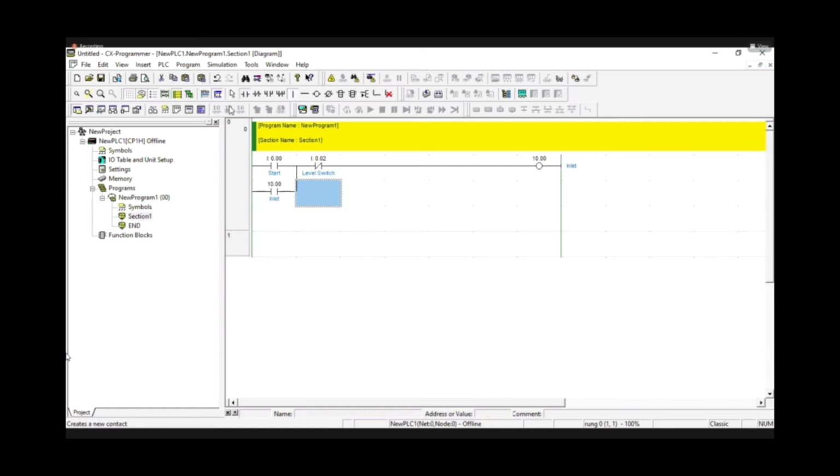So we're going to do the same thing. Now, a lot of times when persons are wiring up the circuit and have put in the code, they put the other one down here, and it is going to accept it. Let me make the point. You put it there and it accepts it. That is wrong. Each of them has a unique number. So this is 0, and the next line in the ladder should be 1.